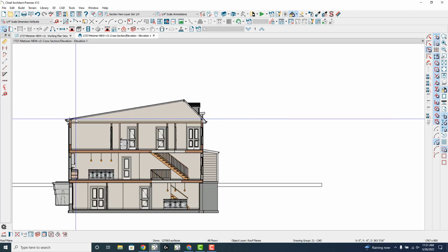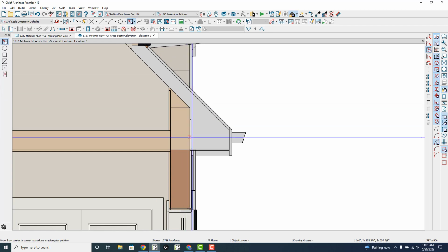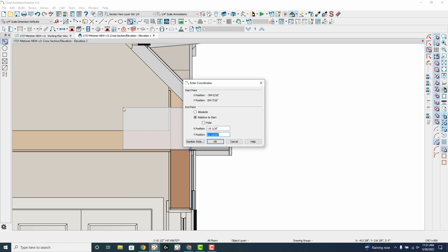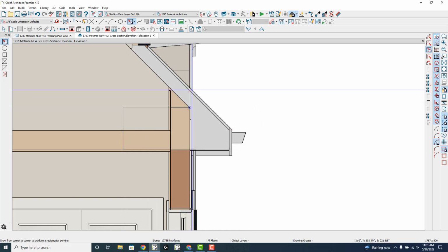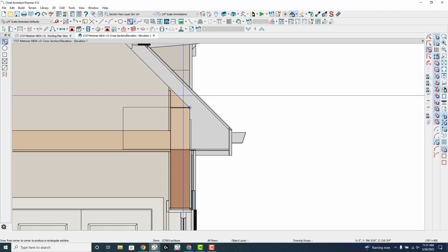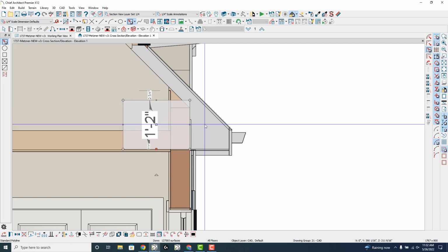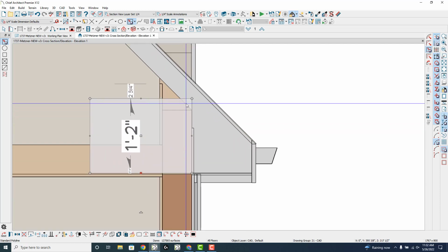There's that one. I'm going to do the same thing over here. Let's see where that 12 is. Yep, same line there. But once again, this 2x4 top chord is a different vertical height at a 12/12 pitch instead of a 2/12. Once again, I'm going to make this construction line 14 inches tall, so I have that 14-inch energy heel.